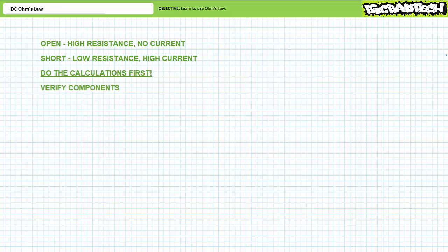Double check your components. Make sure you're using the right components and install them correctly. Read the values on the side. If you can't read the value, use an ohm meter to measure and verify the specified value. Check to see if a switch works before you put it in a circuit. Resistance of a closed switch should be close to 0 ohms, whereas the resistance of an open switch should be infinite. Test everything because lab equipment gets hammered by generation after generation of students. Sometimes out of sheer exhaustion, components, test leads, or meters just die.